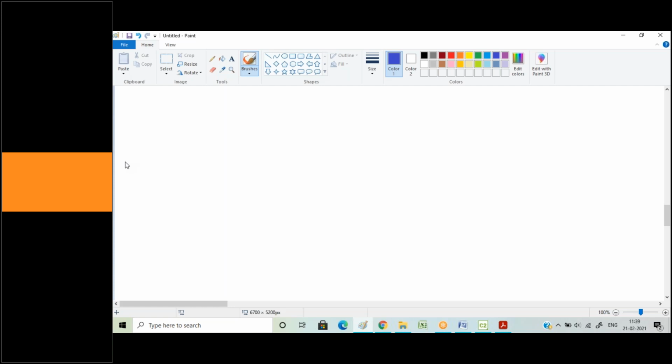Say the formula is suggesting that the span has to be 10 meters for this size of line, like a 4-inch line, and the span between two supports has to be around 7.5 meters as per the formula. If I go with a conservative approach, instead of using 7.5, why don't you better use 6, or 5.5?